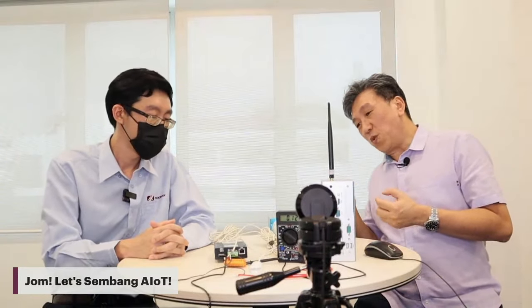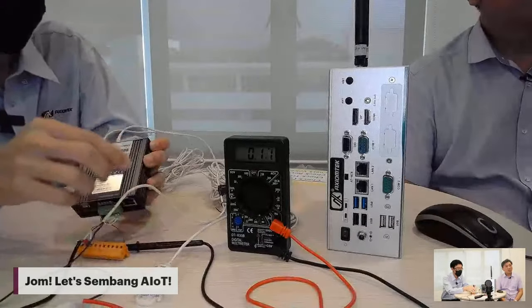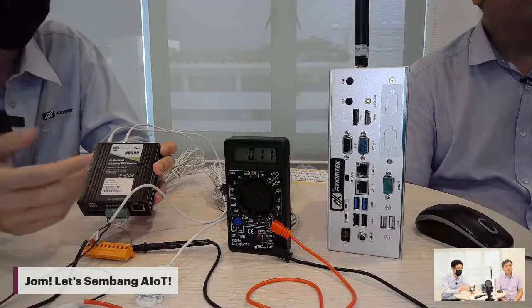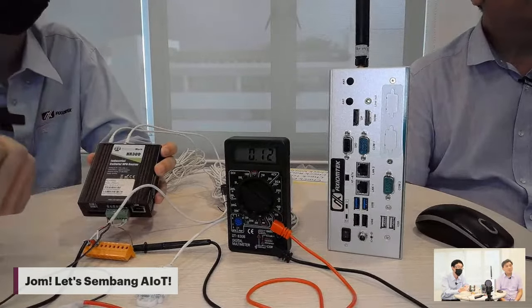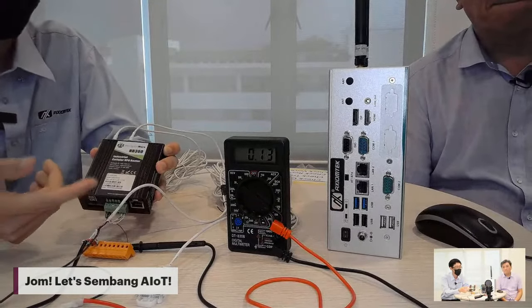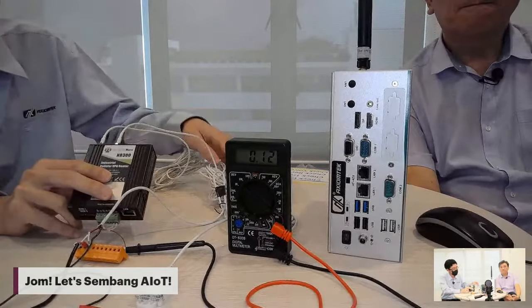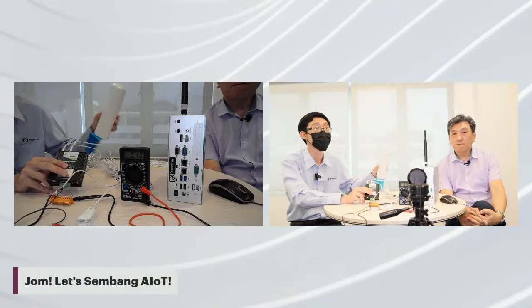That is also one of the gateway routers, the 4G one. So this one is a 4G gateway router. Previously we connected this 4G gateway router to some sensors, and once you put in the 4G SIM card, it can do the Modbus poll either through Modbus TCP or Modbus RTU, and then you can send the data to your cloud. Here we have connected a 4G antenna, a very big one.